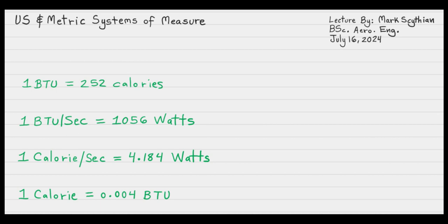And so what correlates to the calorie per second, 1 calorie per second is 4.184 joules per second, or 4.184 watts of power. So that power could be any type of equivalent. It could have come from electricity and then went to a heating element and then became heat, electrical to thermal power. It could have been from any other power source. It could have been even sound power refracting against the material, and then the efficiency losses become heat as well.